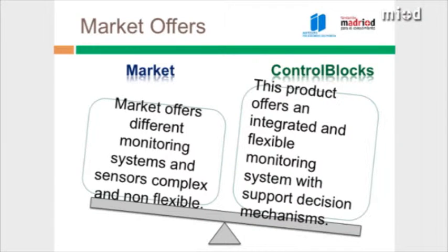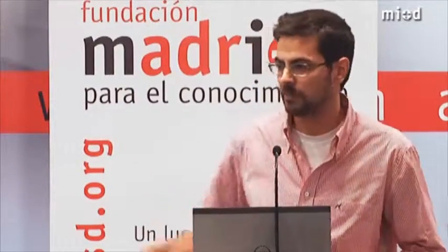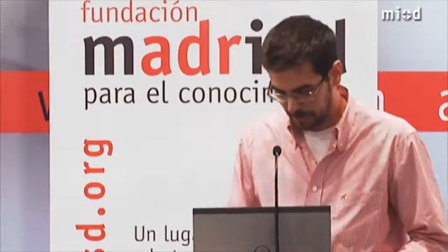For example, if the humidity is less than 80% and the clock time is between 8 and midnight, we turn on the water pump system. So we intend to mix the physical actuators and sensors with digital sensors and actuators. So, for example, if I post a message on Twitter with some kind of format, the water pump system is turned on.